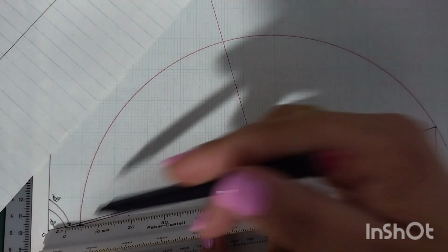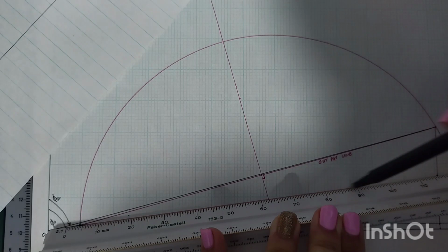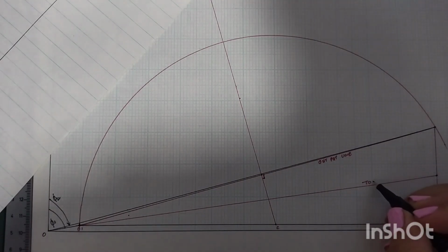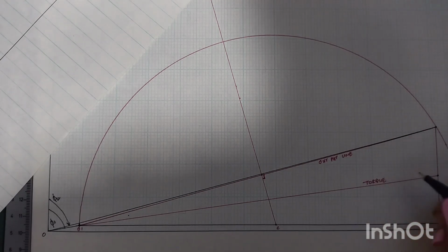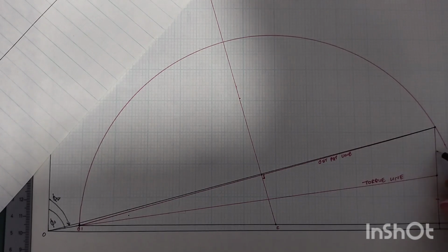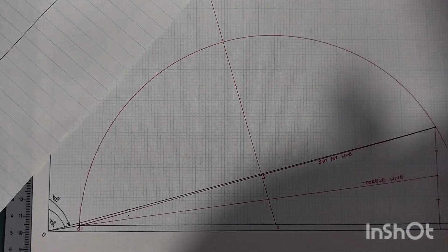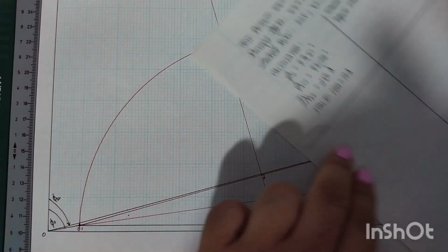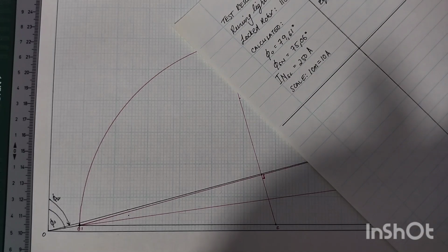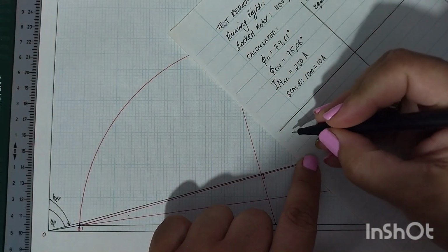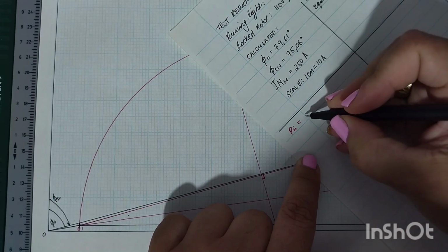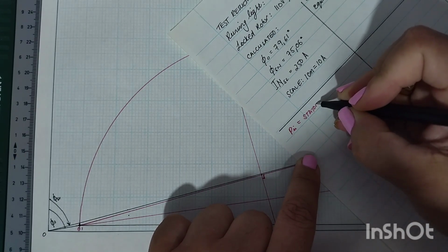Okay, so while I'm busy getting the torque line in here, once you have your torque line, you need to think about this logically. Torque is associated with your rotor. So if there is no actual speed, there would be no torque. The distance from your torque line to the perimeter of your circle gives you the value of the torque or the current. Remember, from the circle diagram, you are taking currents.